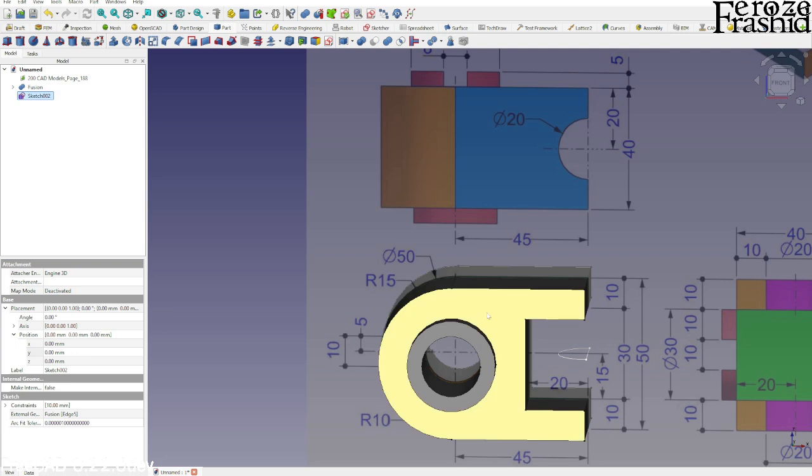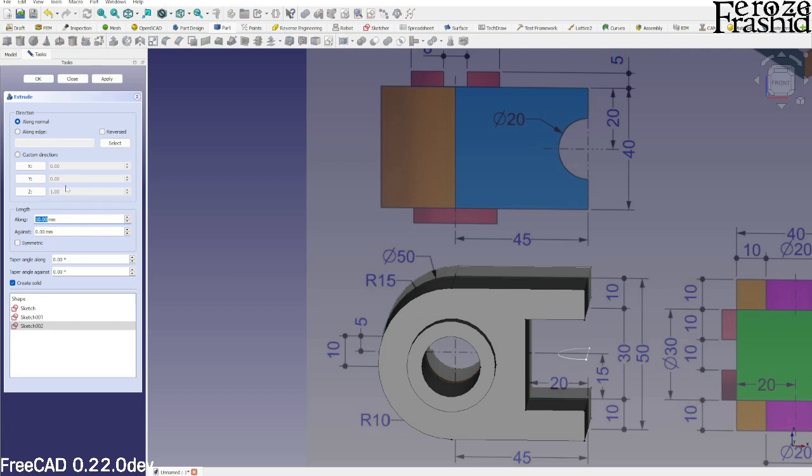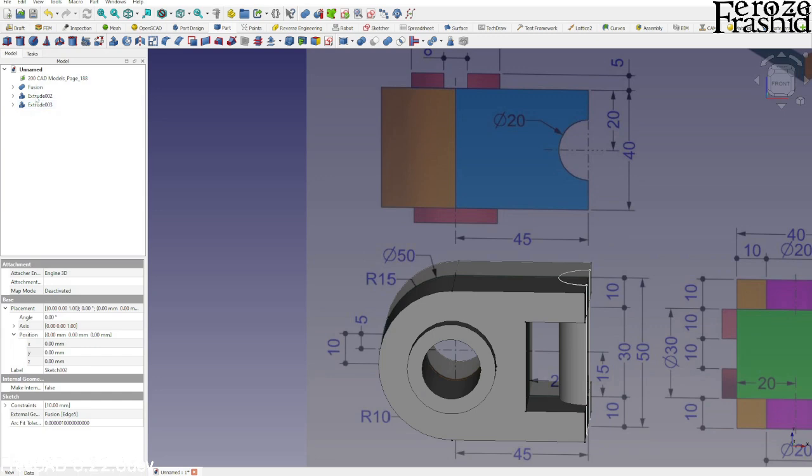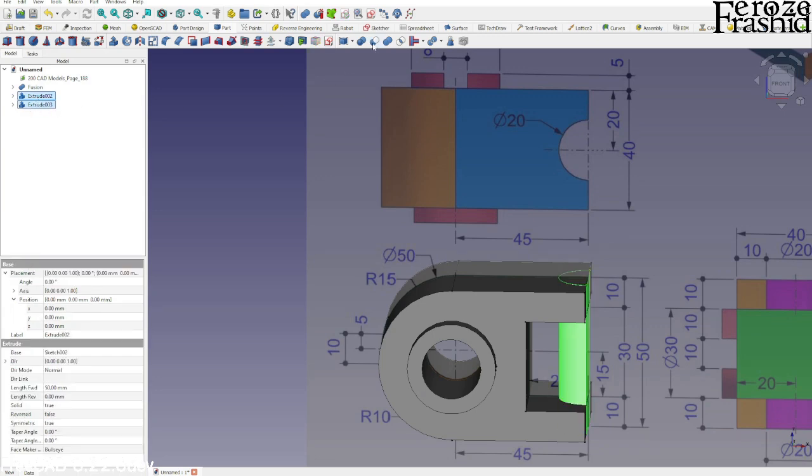Now this is the part where part design is really helpful. So we can just click pocket and it creates the pocket. In part workbench, we'll have to do it manually. So we make that extrusion, right, on both sides, and then make a cut manually.